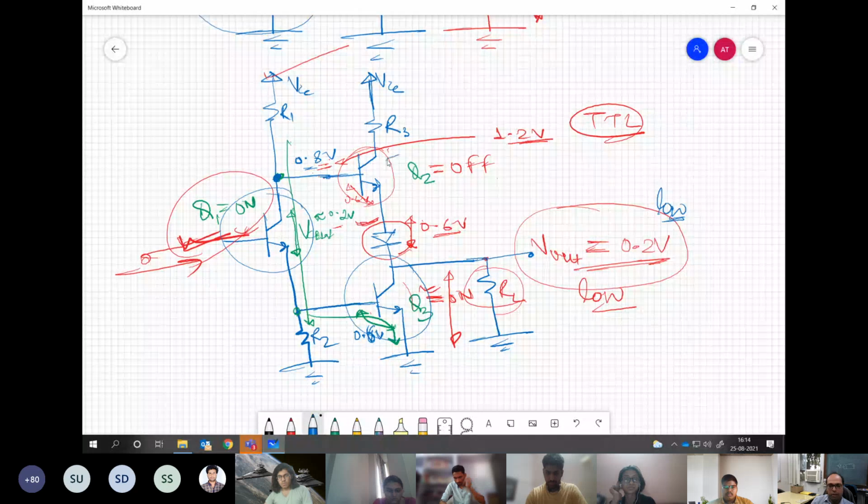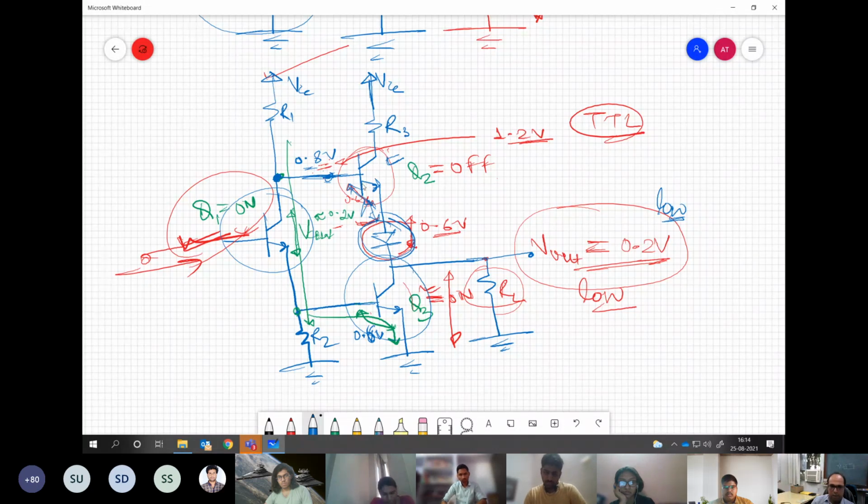And what is happening to the top transistor is that the voltage appearing at this base terminal is not sufficient to break down this additional diode junction. Intentionally, that is why this diode is added, so we do not trigger this transistor by mistake. That is why we reach something around 0.8 volts. However, we would need something more than 1 volt to turn on this junction, at least. So this condition is met, and we are happy that our totem pole structure is working fine.